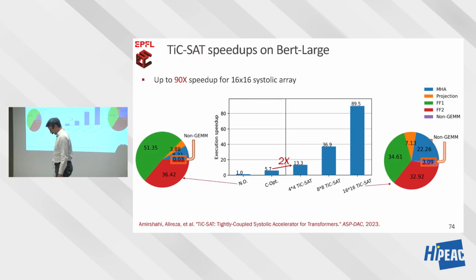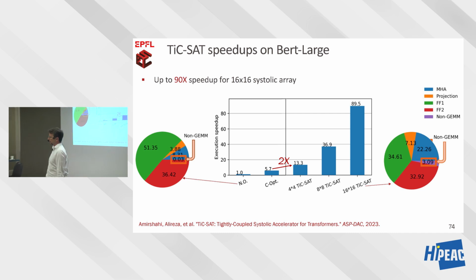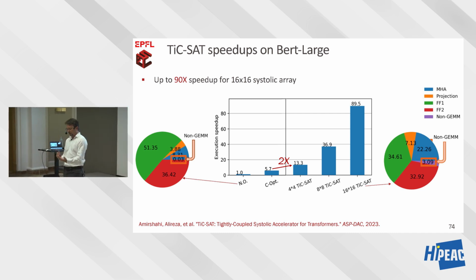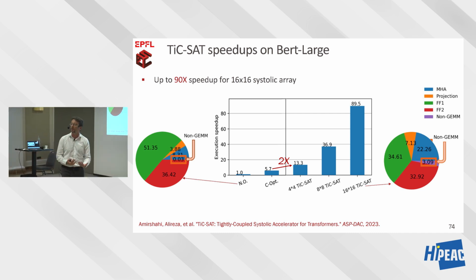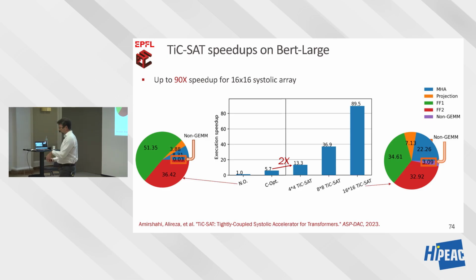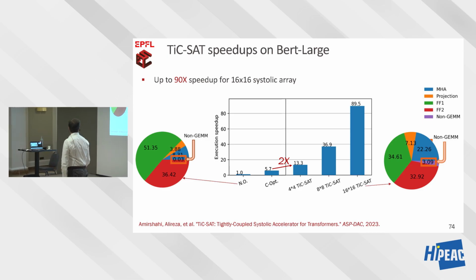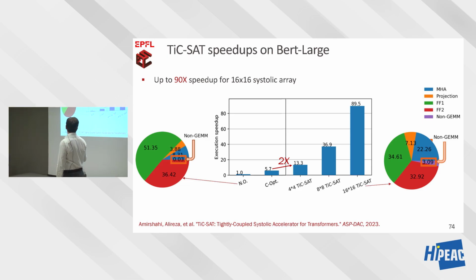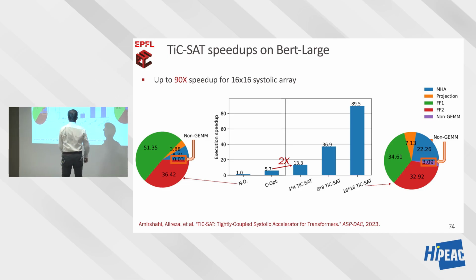So what we found is that, supposing that in our matrix-to-matrix multiplication we may have 8-bit inputs and 8-bit outputs, and that the bandwidth in the processor pipeline is 32 bits, just by using a 4x4 systolic array, we can have a speed up of 2x. So this is how you should interpret this.